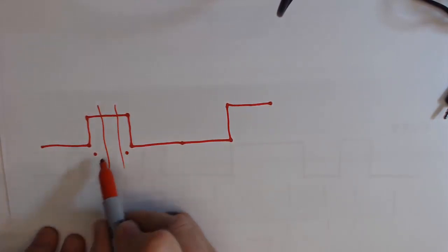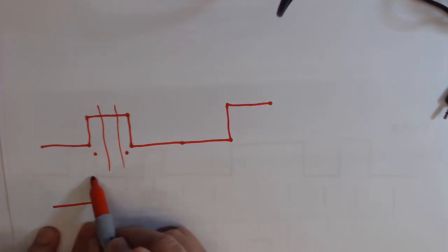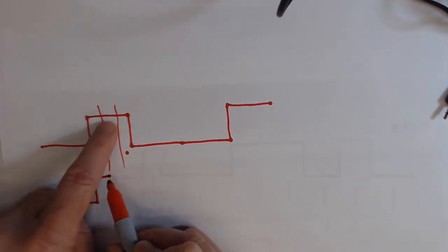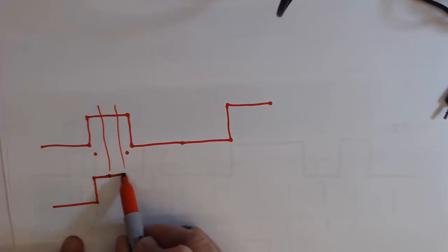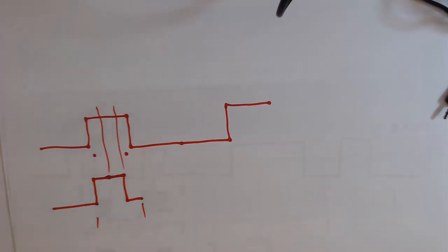So essentially what this one bit would then look like is it would come along, we would have a start bit, look like that. We're then going to have the data bit, in this case it's going to be a logic 1, and then we're going to have a stop bit. So the stop bit is going to go back down to here. So that's the first data bit right there divided into thirds.